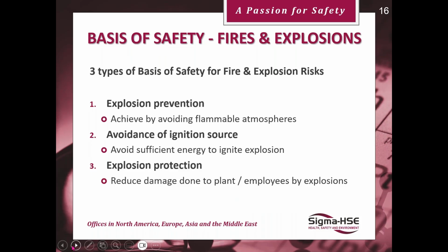Avoidance of ignition sources. The only way you can do this is to make sure you have all the information on what it takes to ignite your product. In other words, avoid sufficient energy to ignite an explosion. Will the ignition source become active? And if it does become active, will it become effective? If the first two can't be chosen, you've looked at it and it's not 100% sure, then you would work with explosion protection.